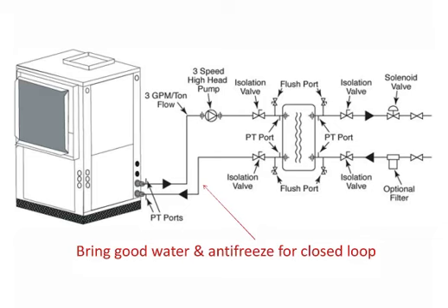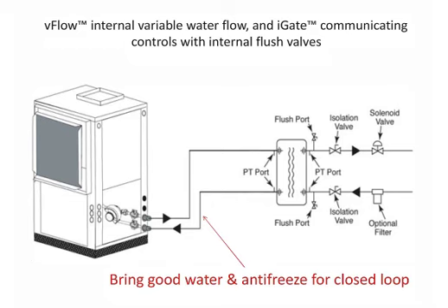Because remember, now between the braze plate and the heat pump, that's closed loop. Always bring that water with you and make sure it's good quality water. Because, gosh, what did you do if you use the on-site water? No advantage at all. If you're using our product that has the internal pump and flush ports, well, you just made your installation life a whole lot easier.